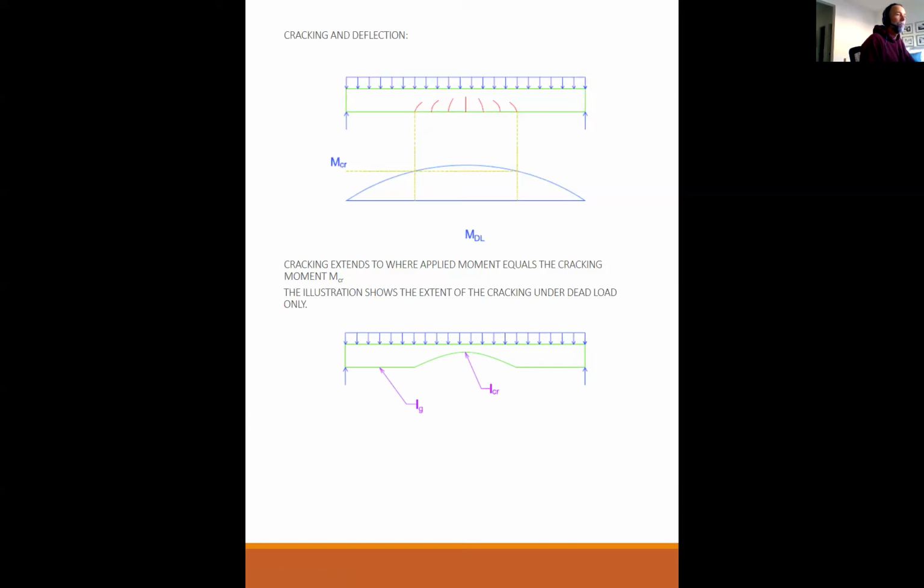I crack represents what the stiffness of the beam is right there at the midspan. I gross is where the beam's not cracked yet, out here beyond the points in the moment diagram where the cracking occurs. So the beam is actually like a non-prismatic beam that is full section, then descending to a minimum section, back to a full section again.